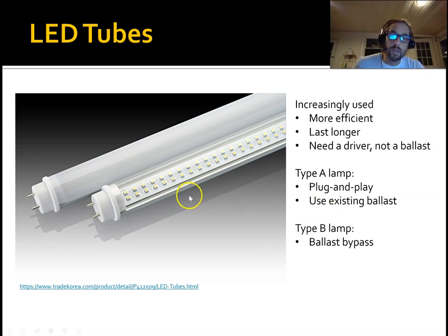and so now they make these tubes that look like fluorescent tubes, but they're actually full of LEDs. And you can see this is exploded, or you can kind of see inside this tube. You can see that there's all these little diodes. Each of these is a diode. Okay, little dots. And these are great. These are much more efficient, over twice as efficient as T12s and T8s. They do make some plug-and-play ones where you can actually just pop out the old fluorescent and pop in the new LED.